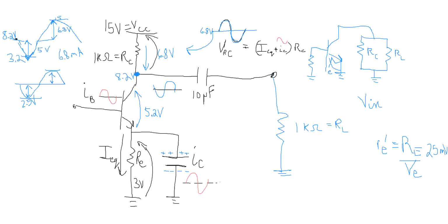That's the DC current. Remember that there is no AC current flowing through our emitter right now because we have that capacitor. So there's something to note about this. This is going to tell me that our gain, which eventually we'll come up with, is going to be related to that capital RE value. Even though it's not in the AC model, it does affect things. Well, let's finish our discussion here. So we see we're coming up with our gain formula here.